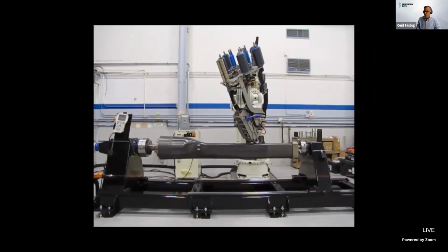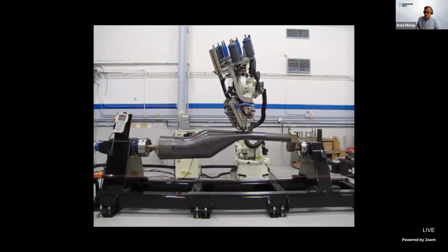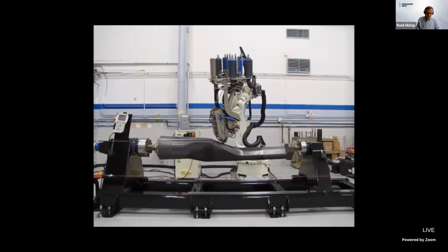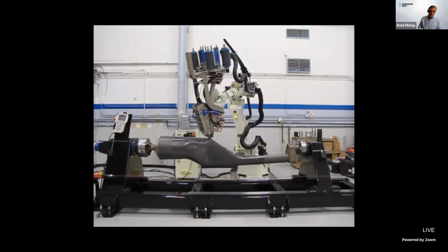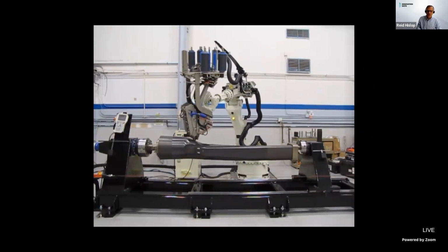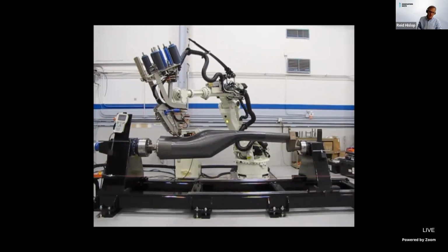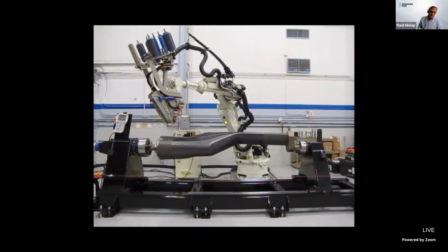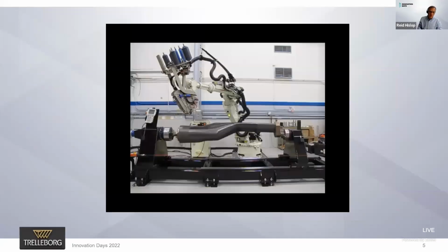In other words, there's no autoclave process, which is a must within thermoset manufacturing. So without this post-process, we call this in-situ consolidation. So basically, we develop these new parts, if you will, kind of on the fly. They're on a tool. When they're completed, the material is allowed to cool. The tool is removed, and that part is ready for production.